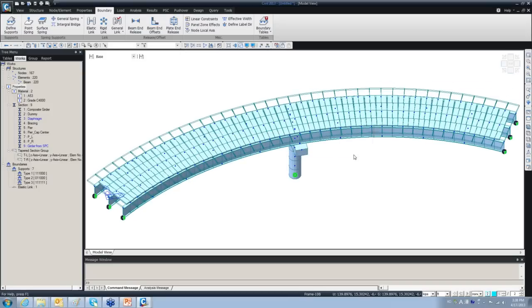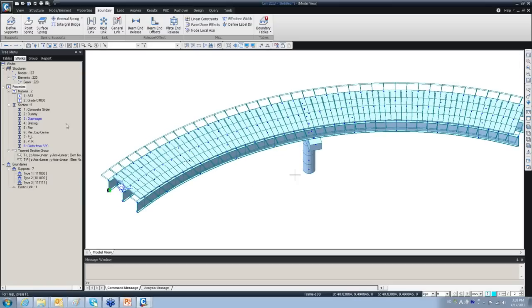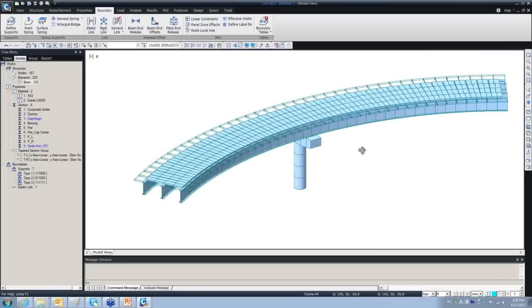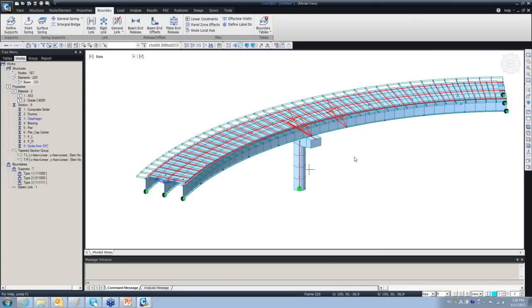If we go to part 2 of the modeling, which means here, if you check this status here, under the element we have only beam, which means the entire modeling is done only with beam elements. Now, what if you want to use a plate element to cover the top of this girder to represent the concrete? So that way, let me just quickly change the model for you. We are just working on the same model, but I want to change something for you guys.